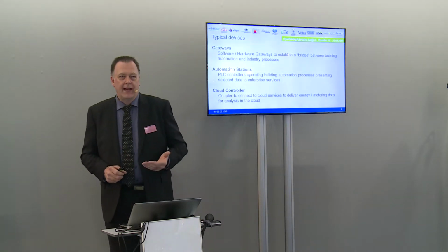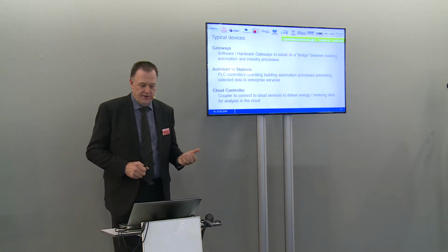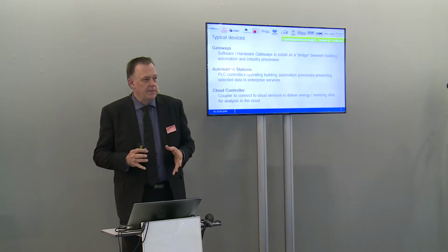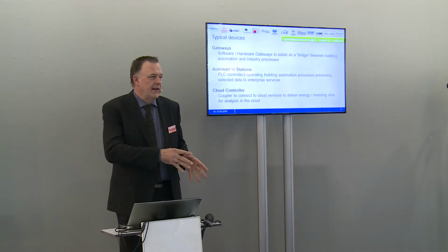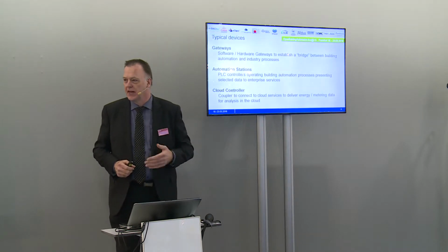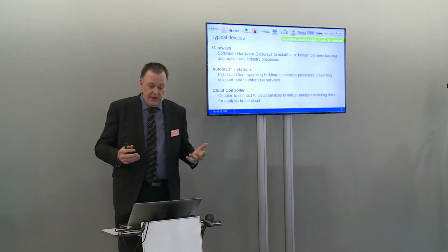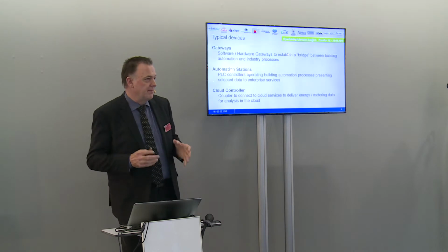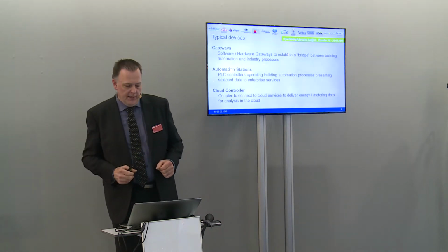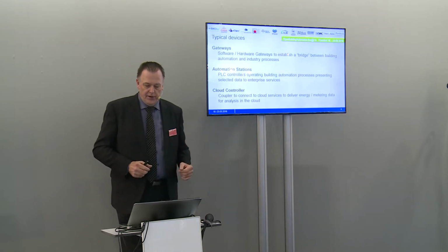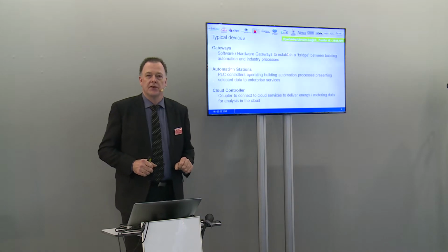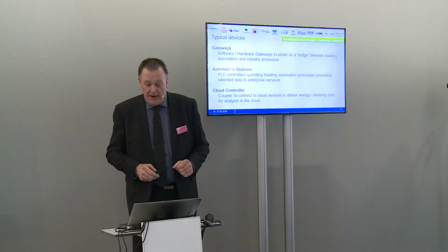So this is a typical gateway. The gateway was provided by the company Connexsoft from Munich, and this gateway now models the BACnet data into OPC UA. But of course also automation stations like PLCs, like DDC controllers may implement this mapping profile and may bring the data directly to OPC UA. And of course they can also work on the automation level and building automation using BACnet.